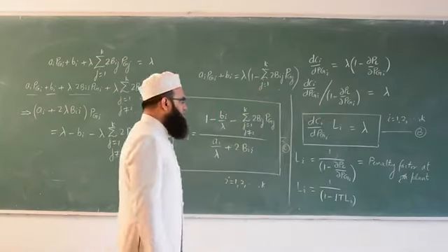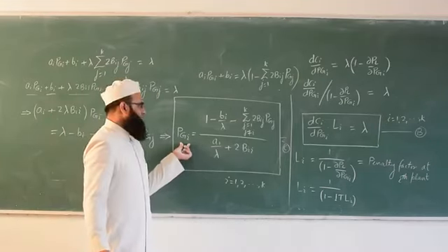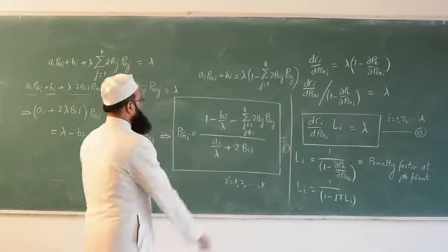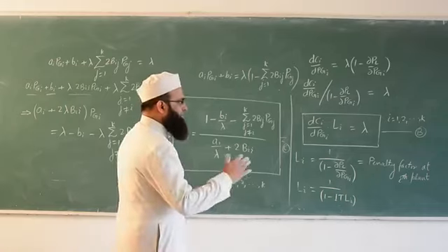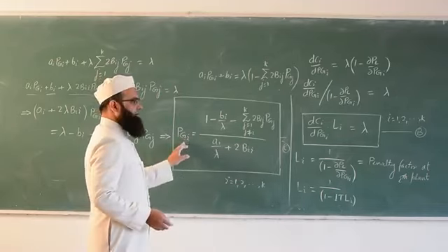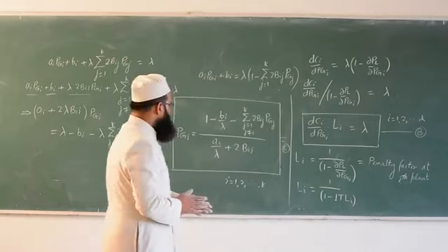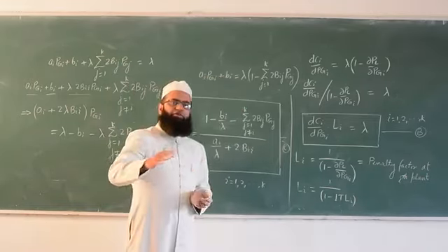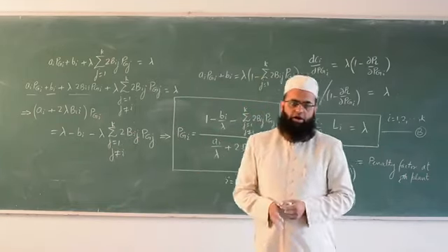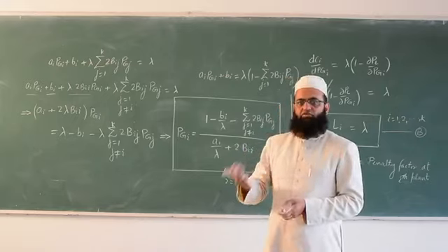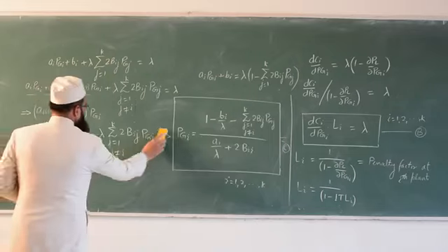Equal incremental cost criterion condition can be used to guess initial values of PGI, and iterations will be started and PGI will be calculated. At each iteration, we will check the corresponding changes in PGI in the previous iteration and the next iteration. If the difference of PGI in the present iteration and the previous iteration is within tolerance, we can stop and take those PGI, or we may write the various steps.